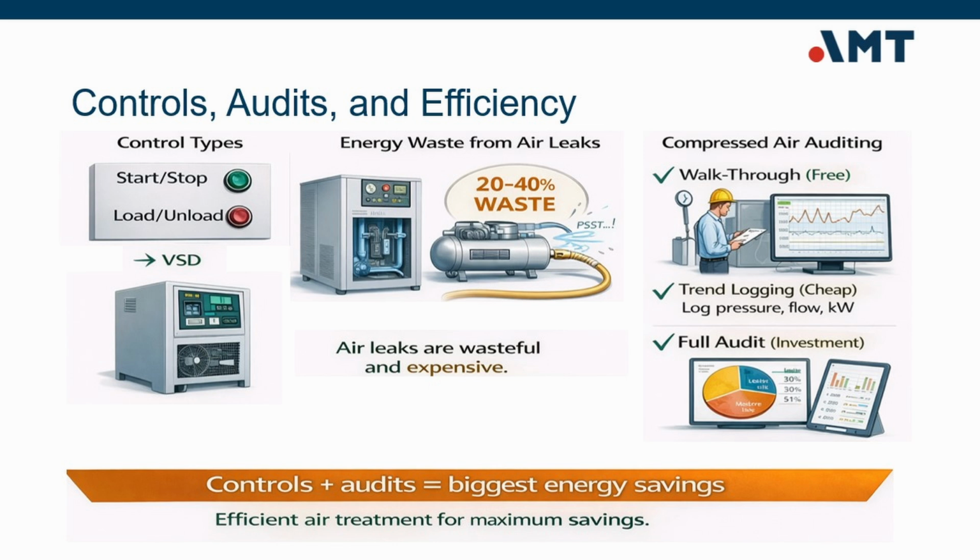This is where audits come in. A simple walkthrough assessment can identify obvious leaks and control issues. Trend logging, monitoring pressure, flow, and kilowatts, provides low-cost insight into system performance over time. And a full compressed air audit offers deeper analysis to quantify losses, optimize controls, and right-size the equipment.